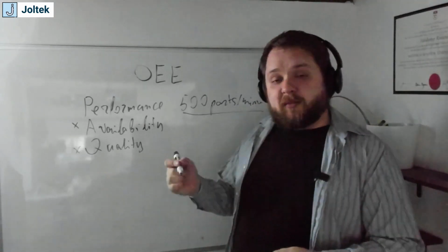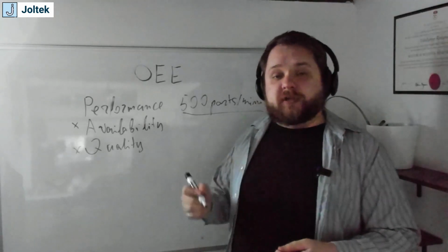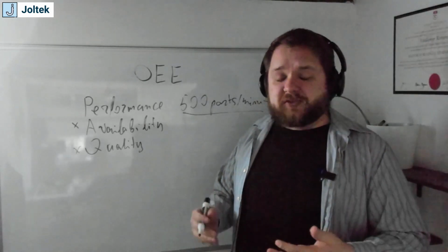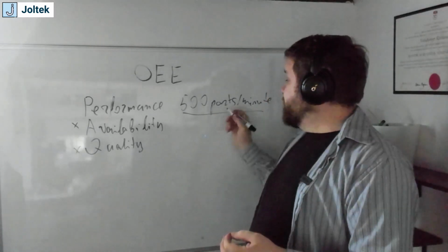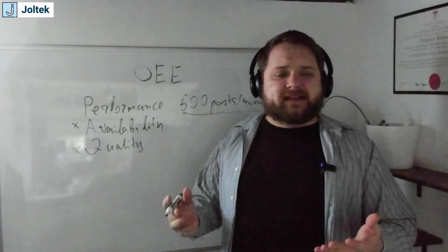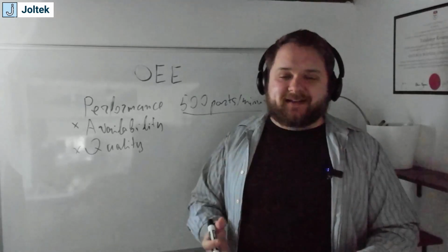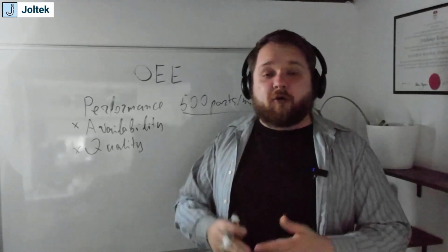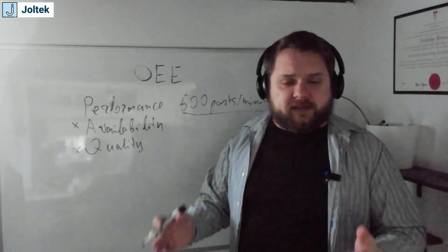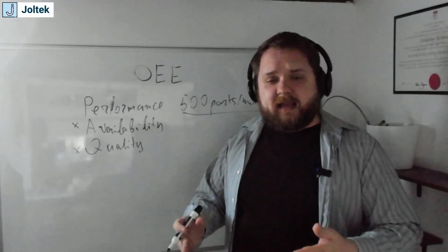And again, remember that everything in terms of OEE, and more specifically MES, usually is going to be time based. So here, when I'm talking about parts per minute, the reality is an OEE reading for a minute is not going to be extremely valuable. You want to be able to make decisions over periods of time, usually, let's say, hours, shifts, days.